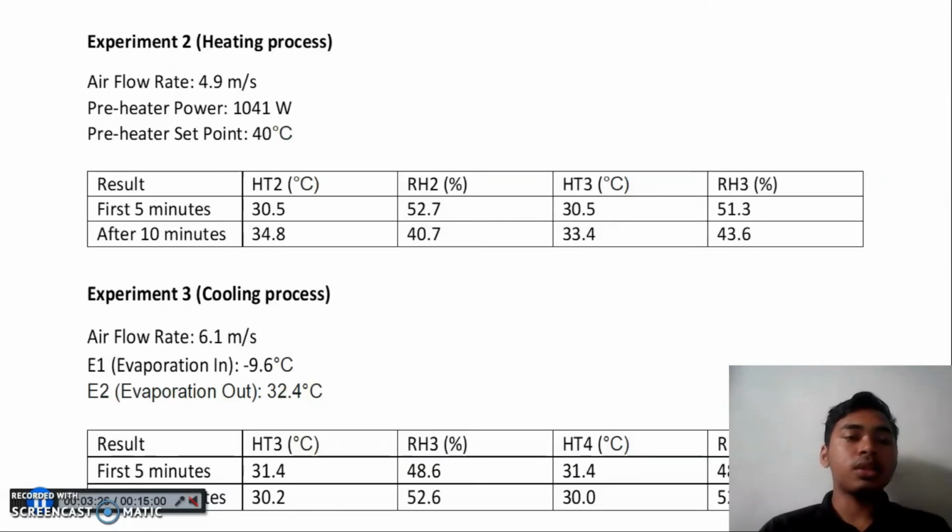Experiment 2 is the heating process. After we open the blower, we need to wait 5 minutes before we record the data for HT2, RH2, HT3 and RH3.